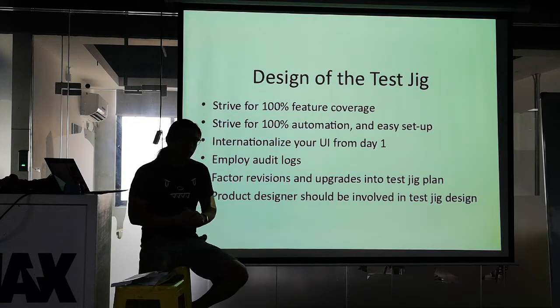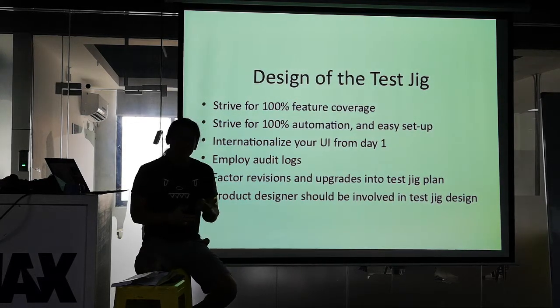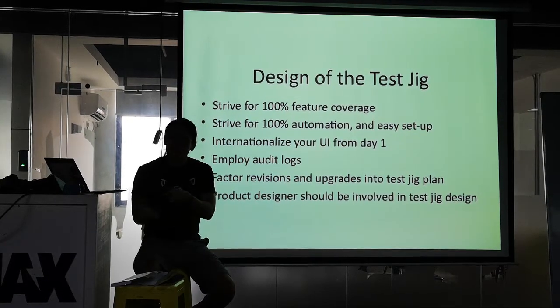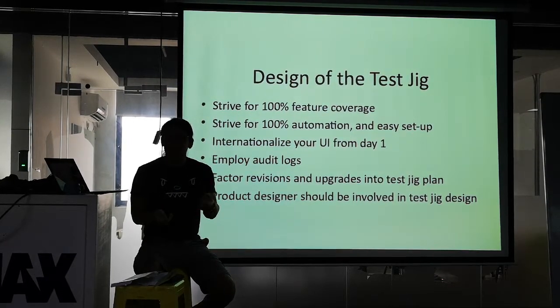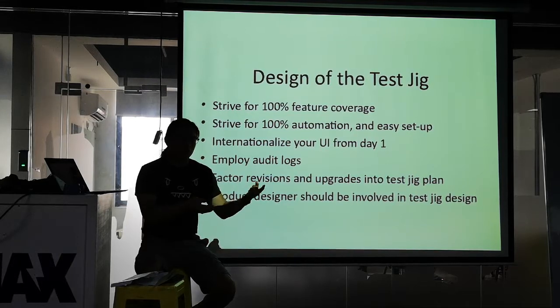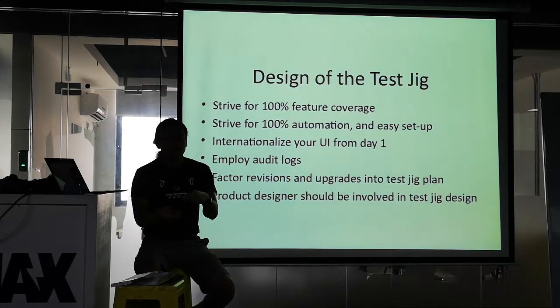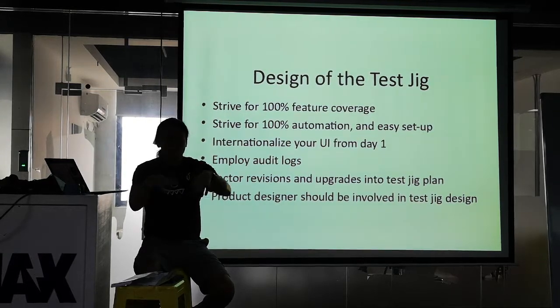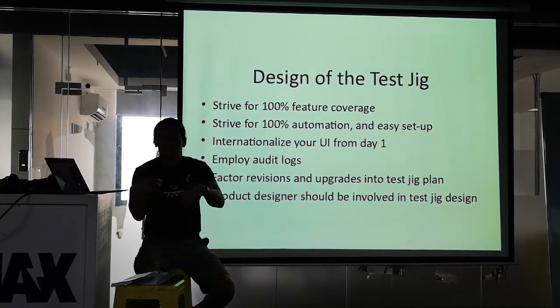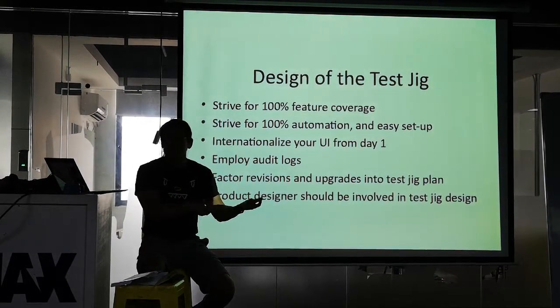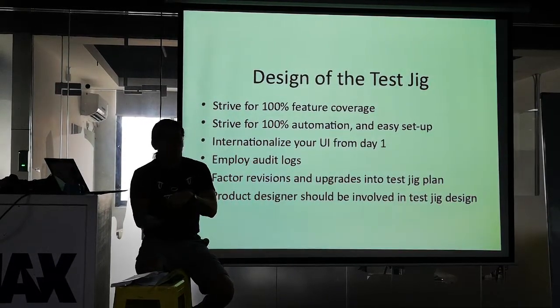Ideally, you think about what happens when your tester needs to be updated. A lot of times the firmware inside your device needs an update, but that means if you're running in production, you have to update the thing that puts the firmware in there. If your plan is to go to the tester, log in and update the stuff every time you push a new version of software, you're coming to China, going to your factory, and updating the firmware on the inside.